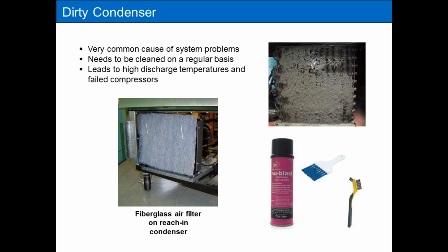So what I found is best is to brush them down. You know, brush in line with the fins. Take a decent brush. It doesn't have to be a real hard brush. It could be a pretty firm but soft brush, if you know what I mean, kind of like a strong nylon brush, and brush it with the fins and get rid of the dirt that way rather than blowing them out.